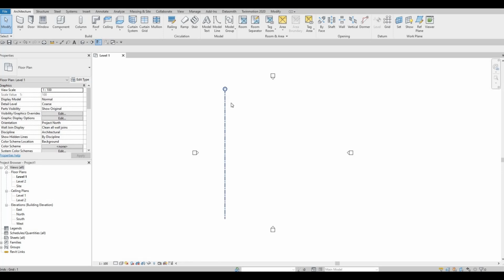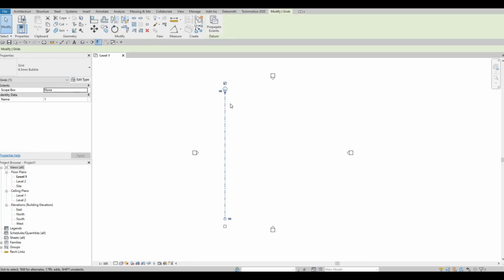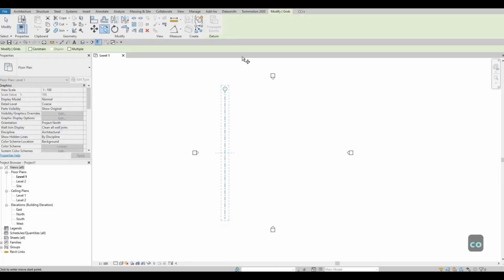You can select that, and then CO, that's the copy command under modify, and this is the icon on that. So that's CO. Make sure multiple is checked. So I'm gonna check multiple, and then I'm going to click it again.